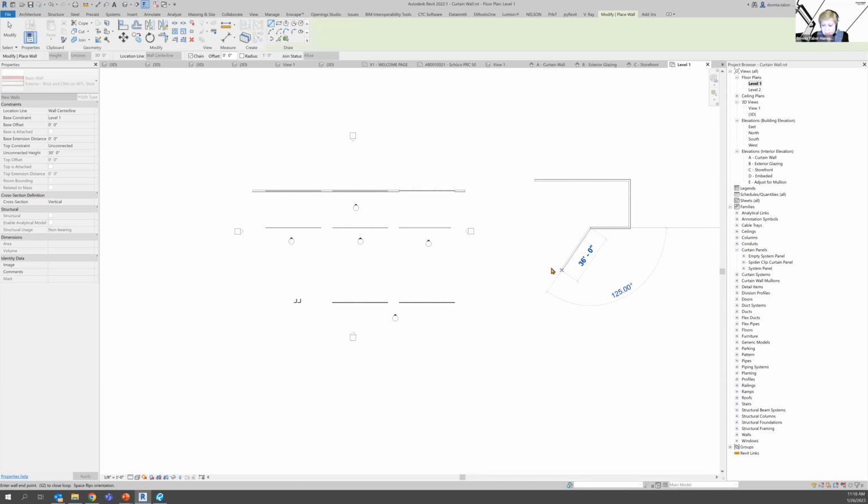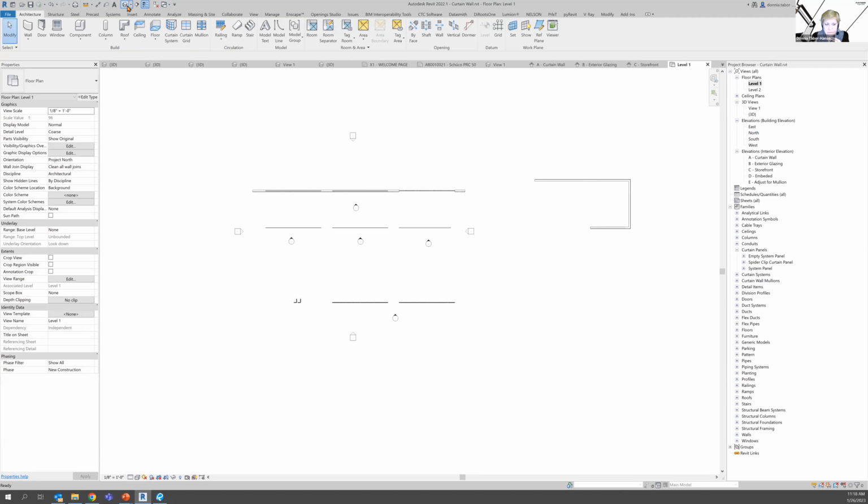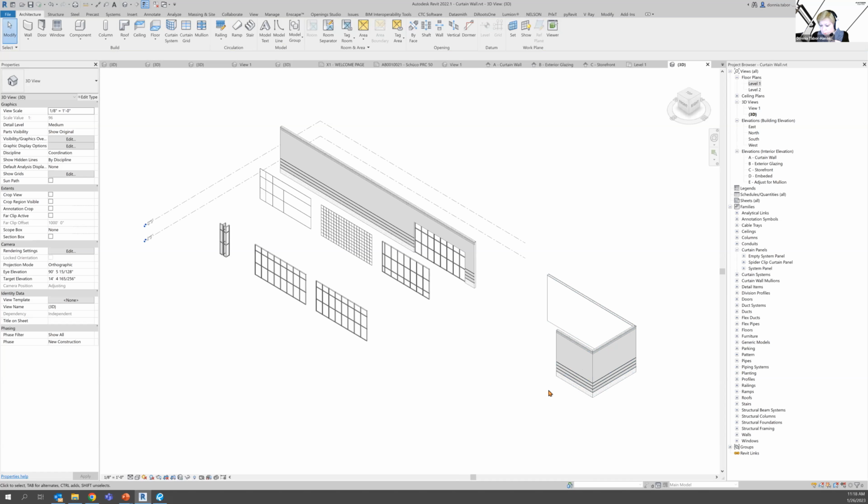And just to give you an idea, let's flip to a 3D view. By drawing around this way, you can see definitely the exterior shows up much better in a brick wall. You can see how the exterior goes out. Well, that's the same thing with the curtain walls. I would go through and draw them in the direction I want them to have their outside face to. And that makes a difference in some of them, especially. Some not so much, but it does for most. So there's your rule of thumb on drawing your walls.